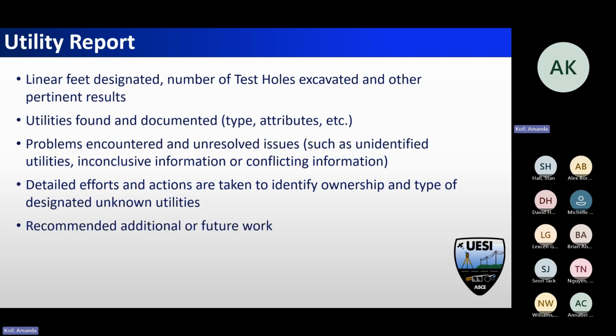Recommended future work. So if you have a level D line you think it's going to be a problem, but they didn't ask for test holes or maybe some level B, that might be time to suggest, hey, you probably need to take a little deeper look at this in your scope, and the next time you reinvestigate this to find out where this line is, because it's going to be critical.